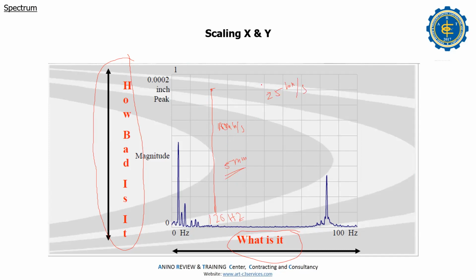Then do you shut down or not? No, no shutdown. Now we have to shut down, we have to clean the fan and remove the residues. So that's the point, sir. Till now, I don't understand how to set the alarm for the vibration amplitudes of the fan. How do I have to decide? It's not simple because it depends on the air. Sometimes the air is a strong wind, then the vibration will get high, and when the wind is low, then the vibration is low.